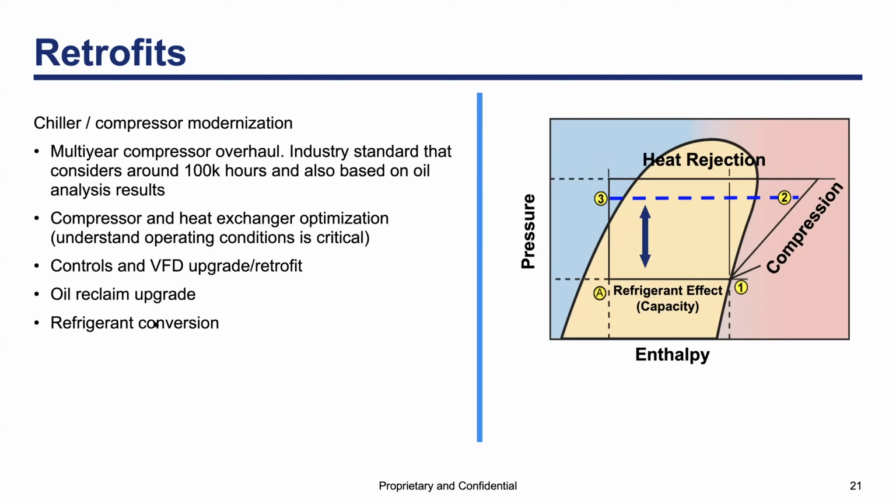One thing that is important to understand at this point, and basically from what I've said, is that you don't necessarily need a VFD in every single motor in the chiller plant to have an efficient system. That's a misconception that in order to save energy, you just throw VFDs in every single motor and we're going to expect 50% energy savings.